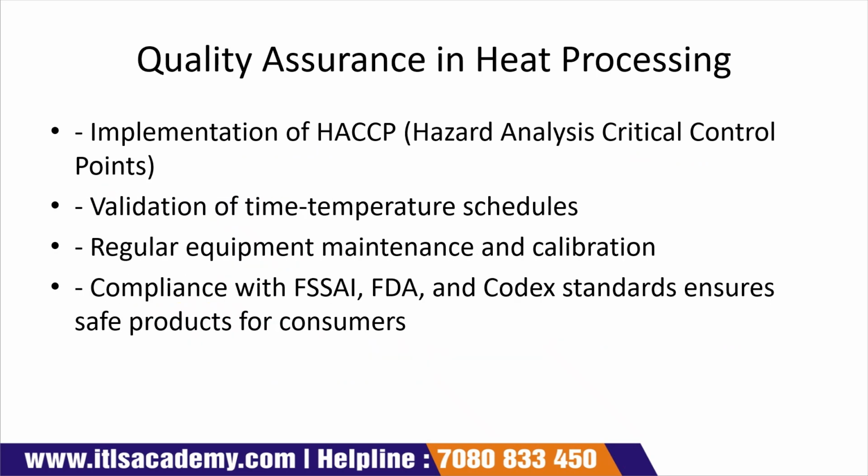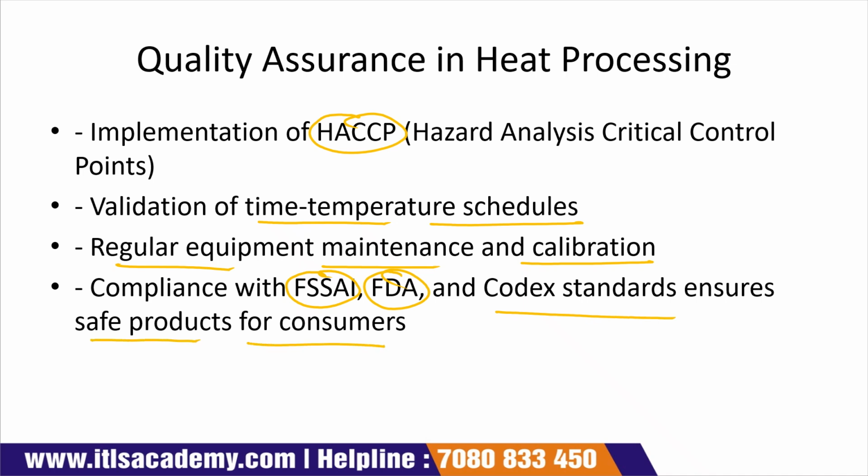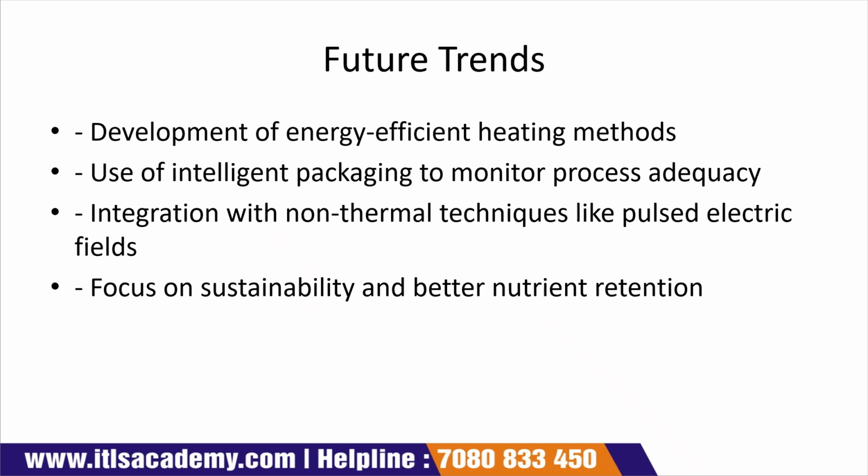Quality assurance in heat processing: implementation of HACCP, validation of time-temperature schedules, regular equipment maintenance and calibration, compliance with FSSAI, FDA and Codex standards, which ensures a safe product for consumers. Future trends: development of energy-efficient heating methods, use of intelligent packaging to monitor the process, integration with non-thermal technology like pulsed electric field, focus on sustainability and better nutrient retention.